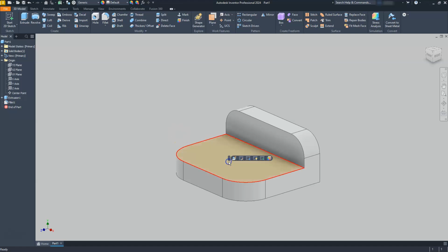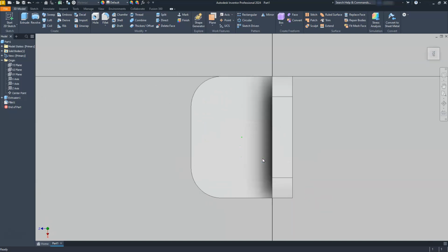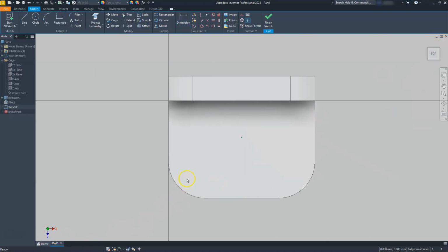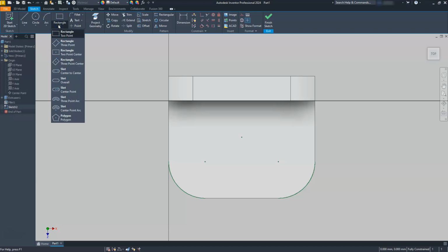So I'm going to create a sketch here. So I'll select here. And then I'm going to click the icon here with the little green plus. I'll go ahead and create the sketch. Let me go ahead and rotate this around so it's looking in the right orientation. And next I'm going to go ahead and project in a couple of shapes. So I'll go to Project Geometry, select these two lines. Alright, so what I needed there was just to get the center dots. These slots are located right along that center.